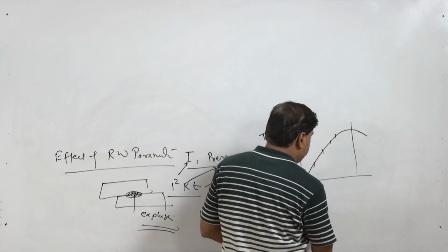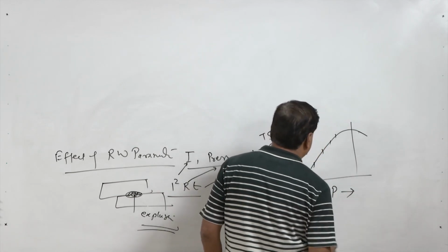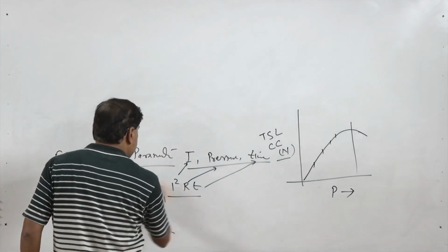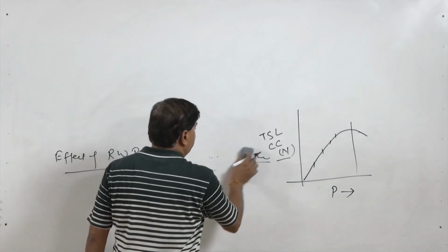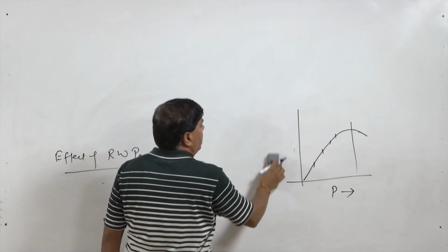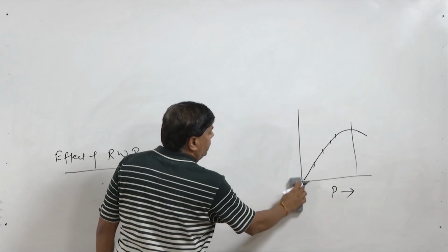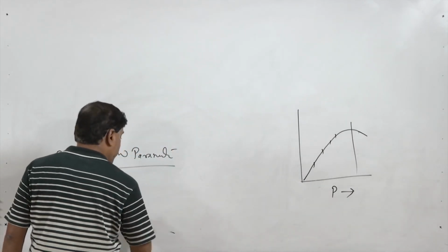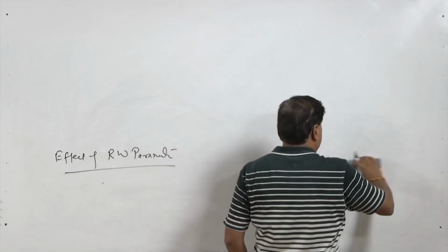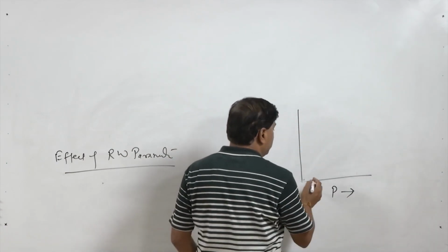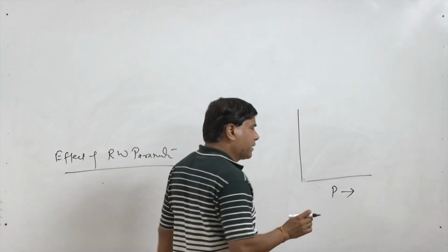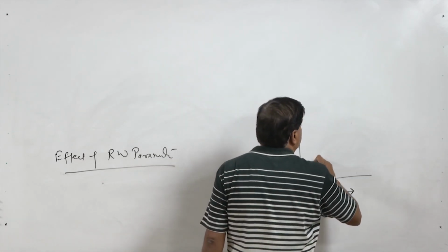So, with the increase in pressure or load, of course we need some minimum contact pressure in order to have good current flow through the workpiece without sparking. Initially when the pressure is less, the current will not be flowing without sparking, so some minimum pressure is needed.